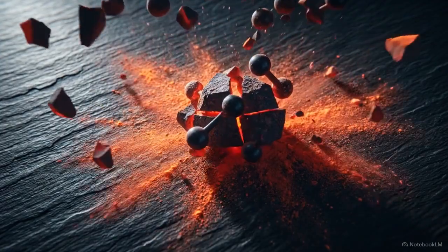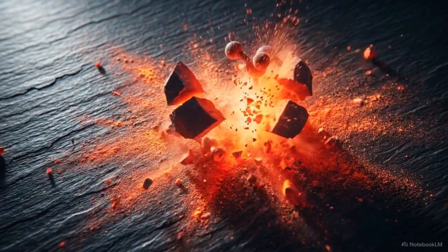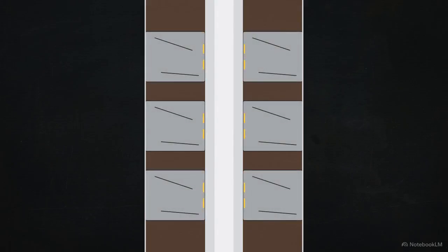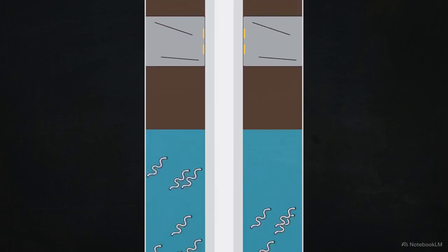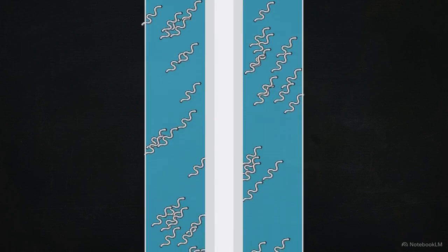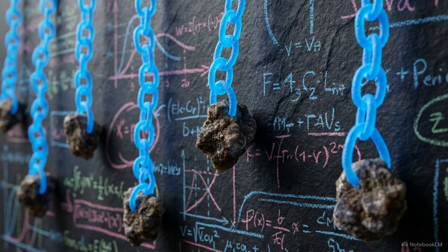The organic bonds within the lignosulfonate deflocculants snap apart under the intense heat. High alkalinity and reactive bentonite clays will fuse together downhole, forming a rigid aluminosilica cement. Preventing this cementation requires a complete removal of reactive colloidal solids and native bentonite from the system. In their place, engineers deploy synthetic rheology.